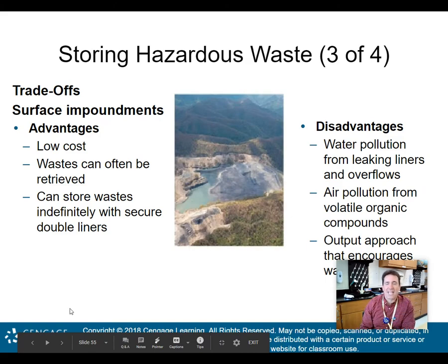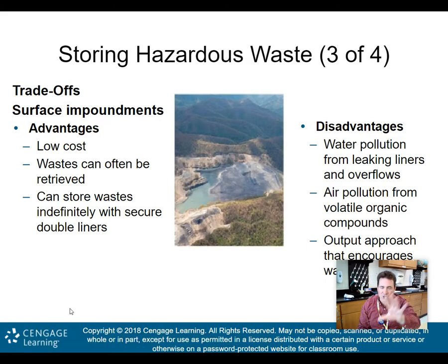Surface impoundments. Again, you need to know these advantages and disadvantages for the different ways that we store hazardous waste, so please have a few of them in mind. Talking about surface impoundments, these are your lined lagoons and lined pits. Advantages: low cost, waste can often be retrieved if needed, and they can store waste indefinitely with secure double liners.